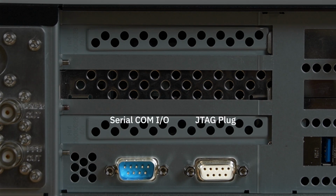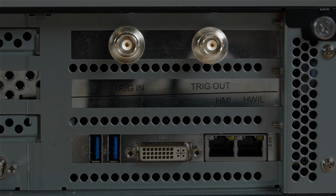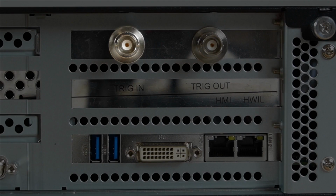Continuing on the left, you've got the serial COM I/O and the JTAG connector. The JTAG plug, a sub D9 female connector, is used to program the FPGA of the machine. Then, on the right of the back face, you've got the interfaces connected to the motherboard. On the top, you've got 2 BNC female connectors to handle the trigger mechanism. On the left, you've got the Trig IN/OUT plug, used to synchronize other equipment with the trigger emitted by the Constellator. Constellator is here used as a master. On the right, you've got the Trig IN plug, used to synchronize Constellator with the trigger coming from an external source. Here, Constellator is considered as a slave.